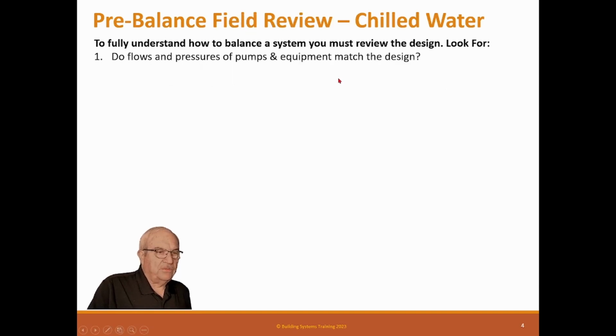Now this is a field review. The first line is wrong there, but basically now when you've done your design review, you're familiar with the drawings, you go to the site and you inspect the site. So do the flows and pressures of pumps and equipment match the design? So basically, is the equipment installed the same equipment that was designed? Do the pumps they actually install have the same GPM as the design? You kind of check all that out, make sure nothing has changed.